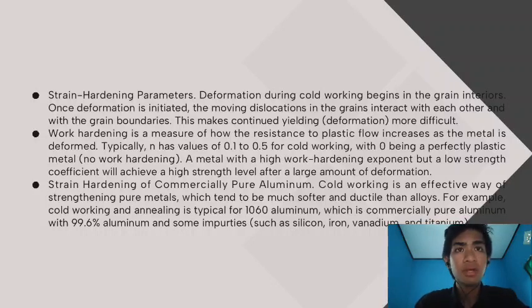This alloy is typically used in products requiring good resistance to corrosion and good cold formability, and where low strength can be tolerated, as in chemical process equipment and railway tank cars. The strength of 1060 aluminum is enhanced moderately by cold working.